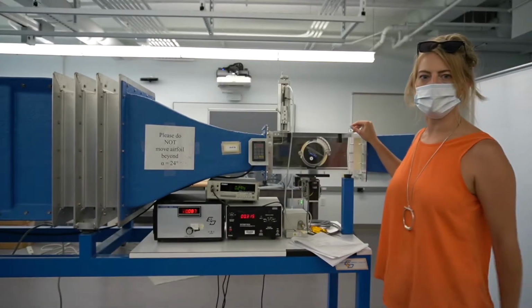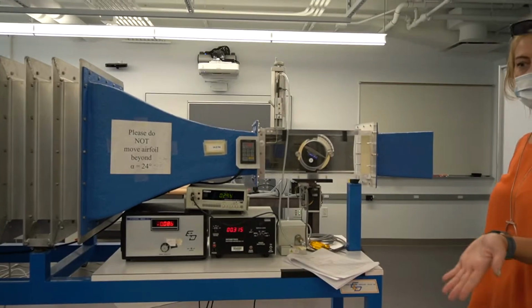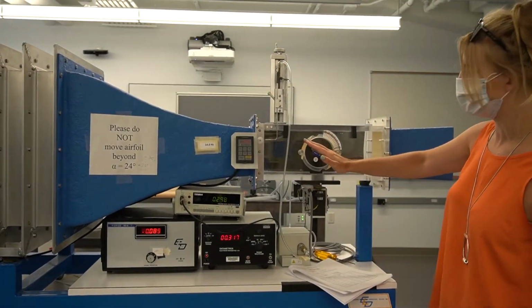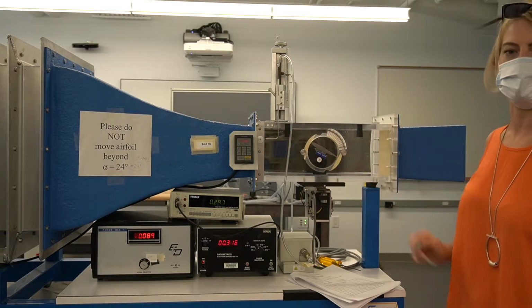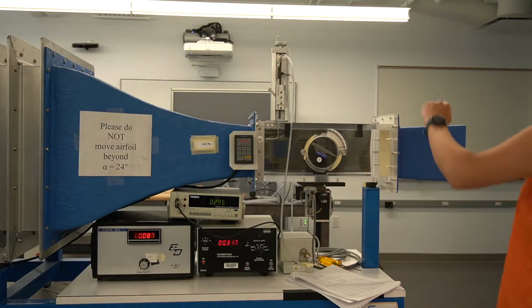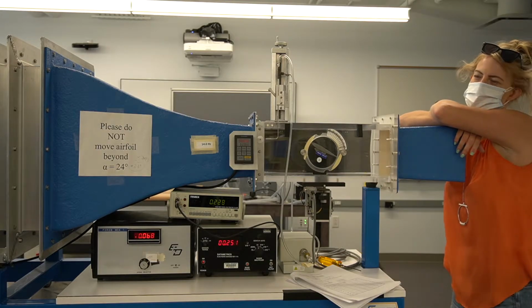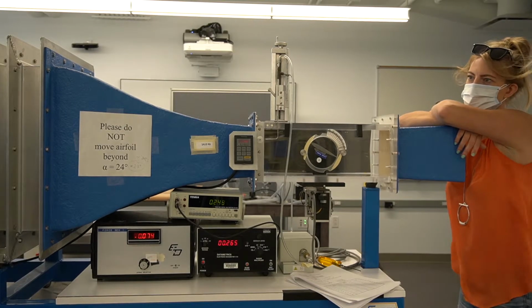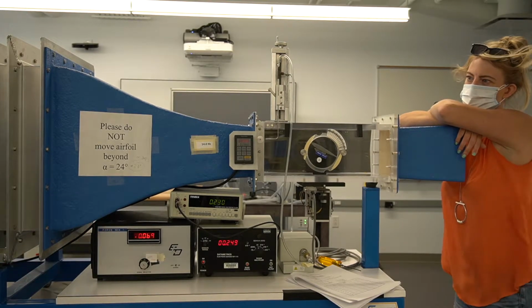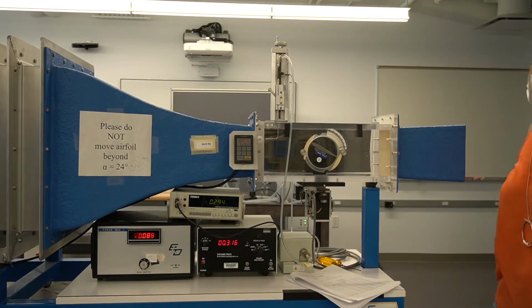So if we have a look at PT minus PS right now, as you can see, it's lower than it was at the start because there's more area of the airfoil towards the incoming flow. But if I was to then stand at the edge of the wind tunnel, what happens to PT minus PS? It's decreasing even more now. So it was 0.296 without you standing there. It seems to be hovering around 0.22 or so with you there.